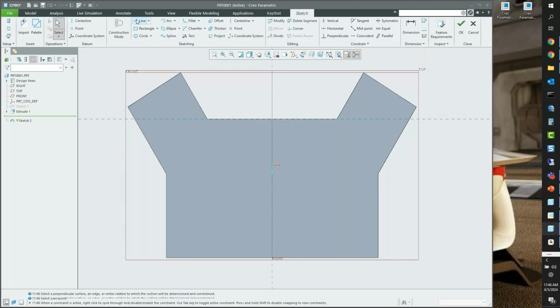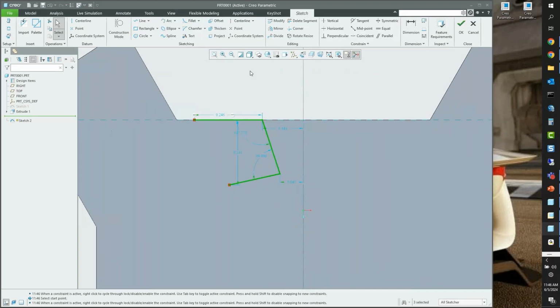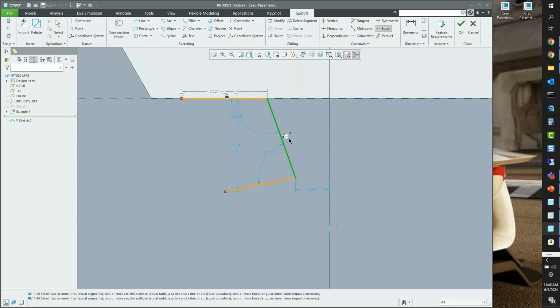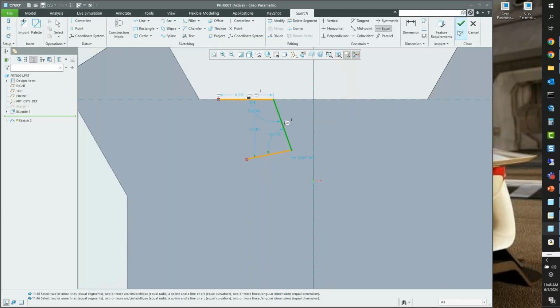If I've got some sketch going on here and I say, hey, the new thing in Creo 11 is that I can lock these. So I can go in here and say, let's make this one and this one locked. And let's make them equal, right? You can see I can turn on that lock display. So that's the new icon for lock display, right? They've added, again, other techniques in 9 and 10 for highlighting junctions and intersections. But that's pretty much it for Sketcher.